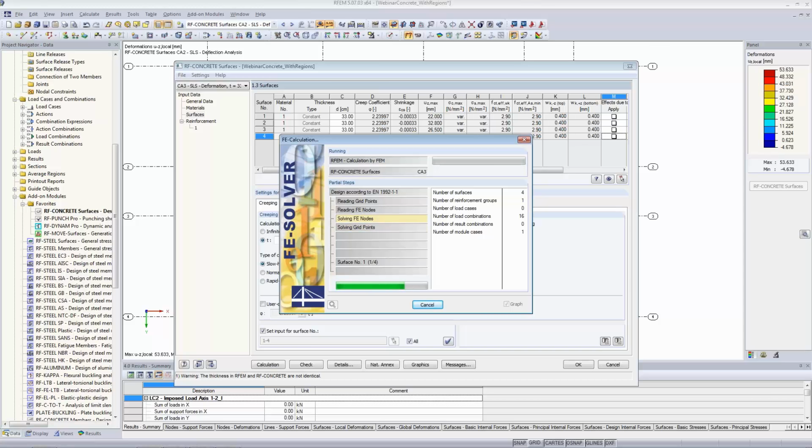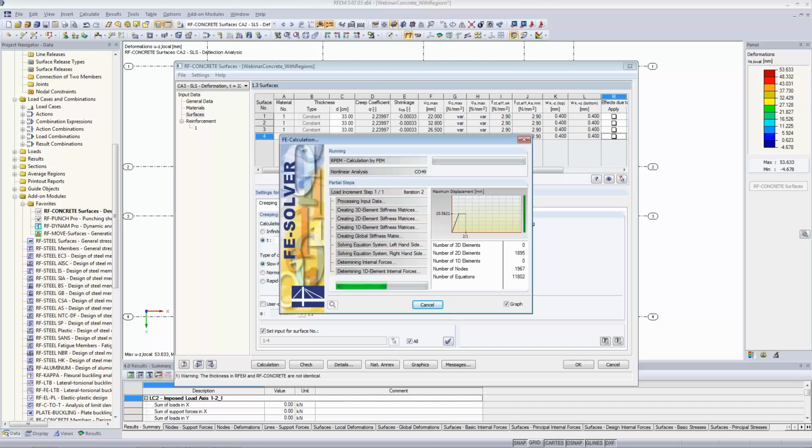After that, we only want to consider one last case. So far, we have calculated the deformation for the final state of the plate, and we have considered the lower deformation limits. There are some stronger deformation limits described in Eurocode 2, which is L over 500, and this is something that you have to use when you have adjacent parts that could be damaged.